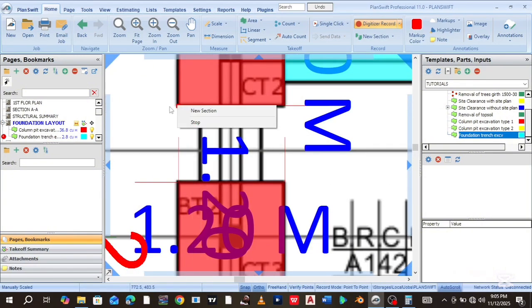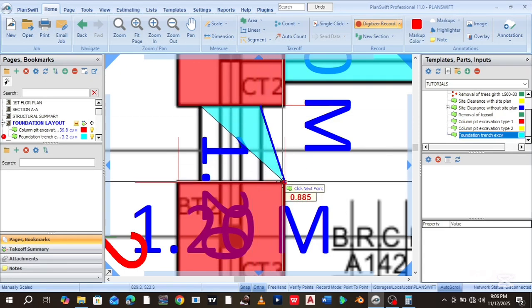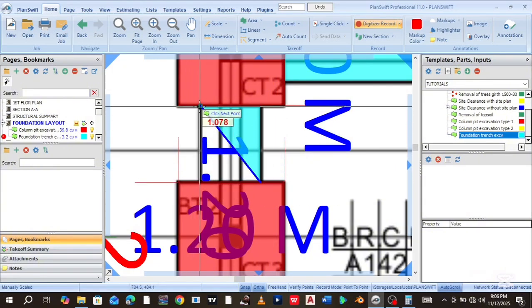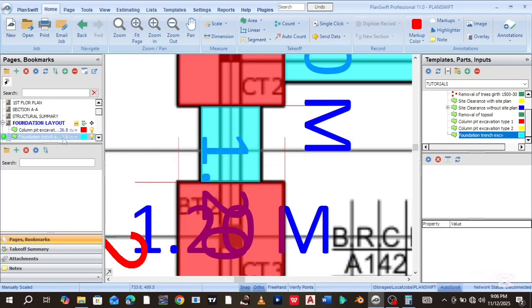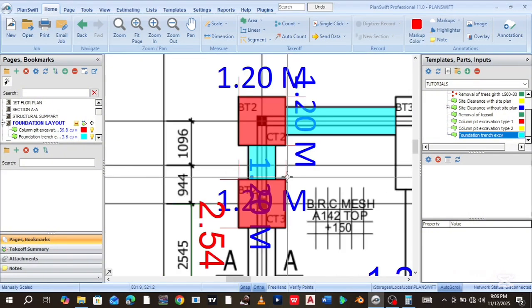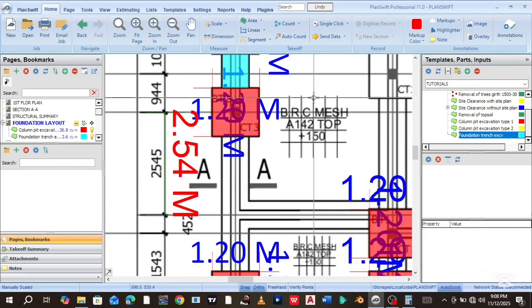So right, left click so that this thing can show if the snapping is not activating. Right, so right click on the background. You can see now it has activated. So all you just need to do now is to drag, click, make sure that it is 675 on the dot, then click. So you can use this as a reference point. Click, use this as a reference point, and click. So you can see now it has increased to 3.6 cubic meters.